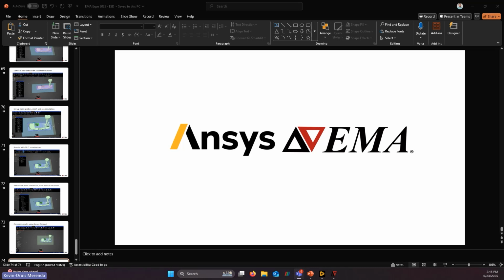So that means that every time you have a harness, like we just did here in our demo, we want to make sure that we fix the grid in that location to not change in size. And so you can actually create and use the variable mesh tool to encompass all the cables and make sure that the mesh doesn't change in that region. So that's also one way to use it.